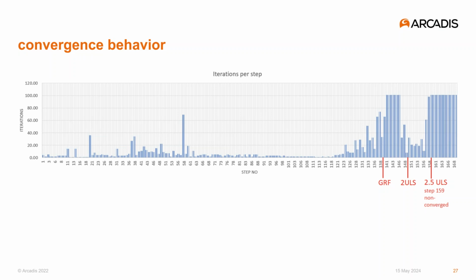And then, when the pre-stress starts to yield, the second non-convergence occurs, and it's not re-established anymore. We still need to see the results to evaluate the reliability of the first series of non-converged steps, but this graph already gives some clue that the ultimate failure load is slightly lower than 2.5 times the ultimate limit state loading.